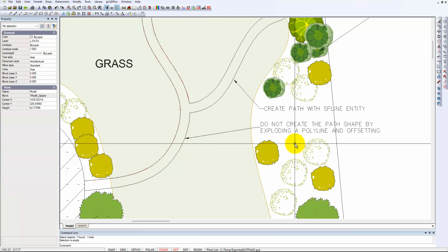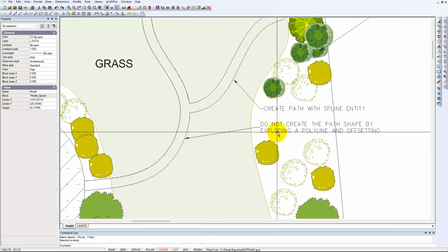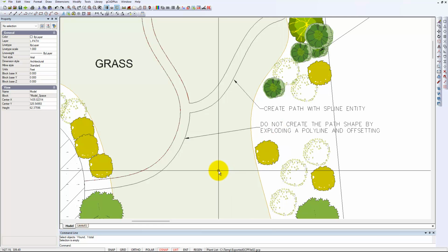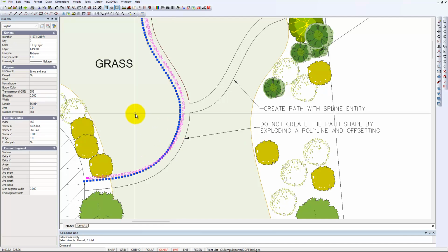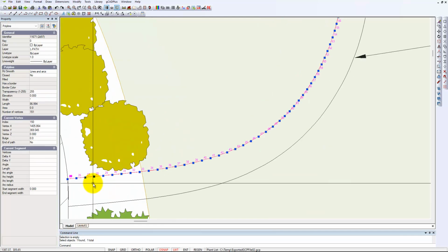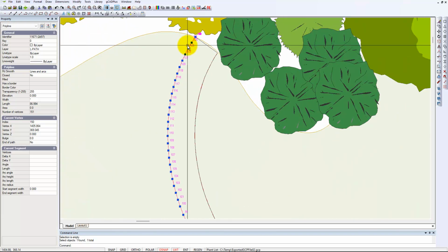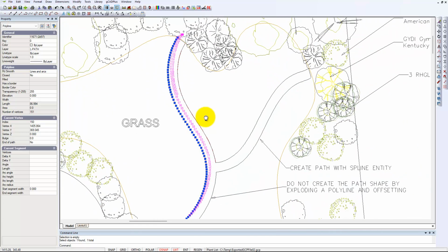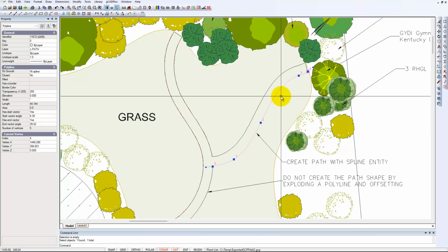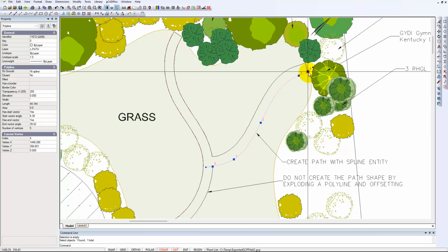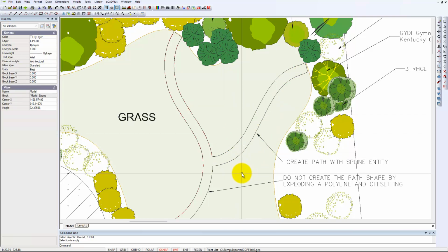We often see quite large drawings from our users and the users are puzzled as to why simple drawings end up being relatively large, and this is often the cause. If I click over here, can you see literally dozens and dozens of vertices in there, 124 vertices on that little segment, whereas if we come here, see there are very few vertices, in fact 4 vertices in the whole design, so that's going to be much more efficient to work in that way.